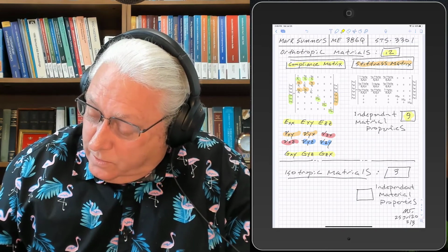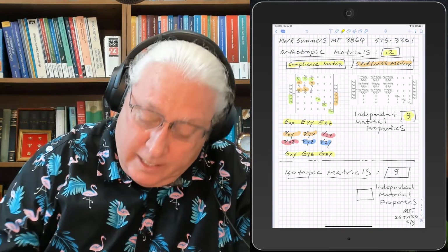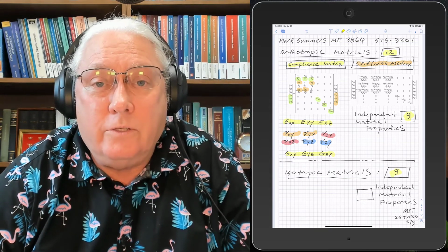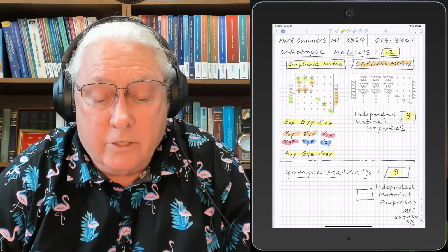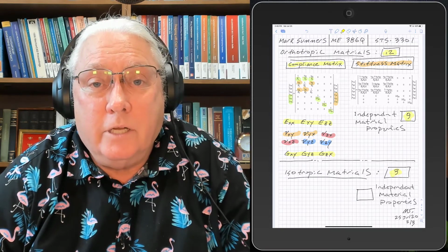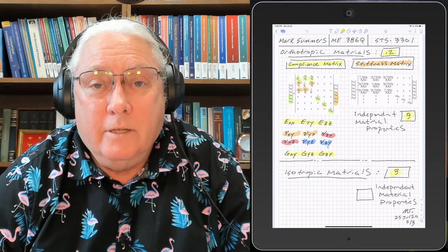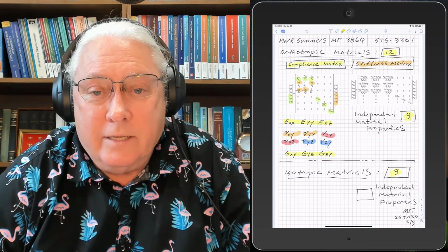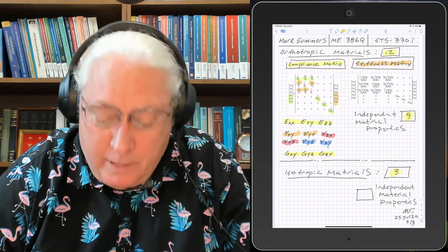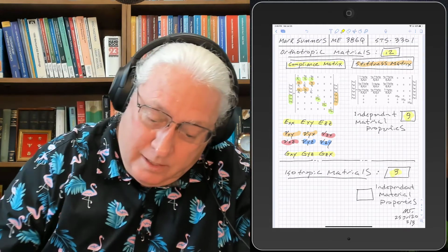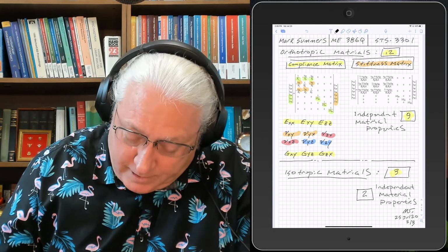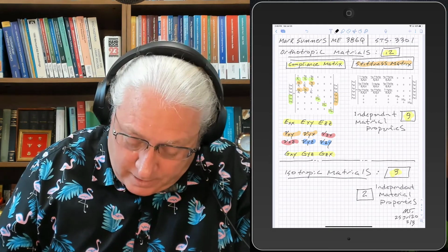All right, so let's go back to the isotropic material to kind of close the loop on that. We talked initially that there was 3 different parameters. There's a Young's modulus, a shear modulus, and a Poisson ratio. But it turns out for similar reasons, there's only really 2 independent material properties on isotropic materials because of this relationship that I can write down here, if I can remember it.